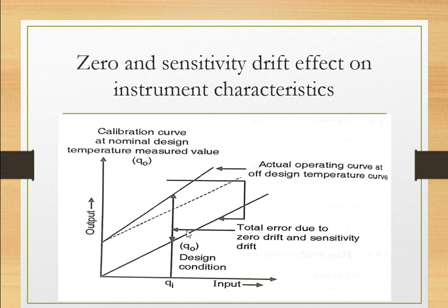If you see the strain gauge, we can say that the ambient temperature changes cause a change in the resistance of the strain gauge. I am talking about just a strain gauge here because I am giving you an example. We know that the change in resistance is the most important parameter in strain gauge measurement, so that may affect your readings.